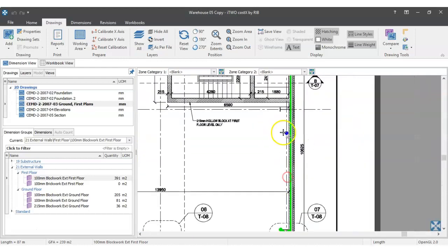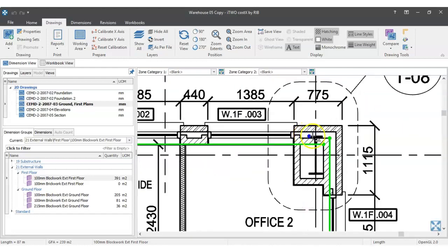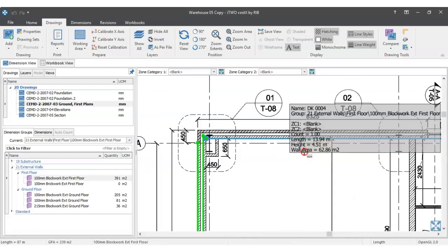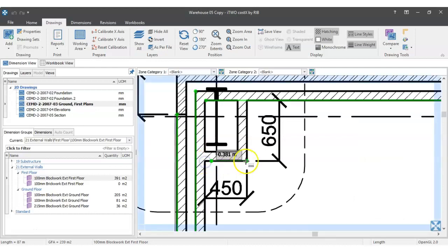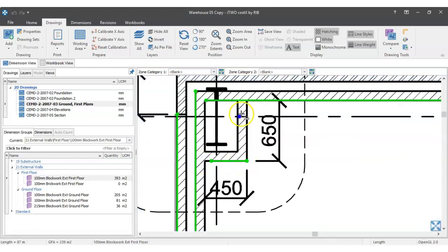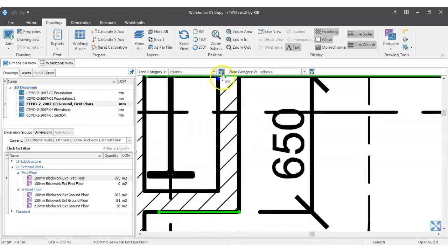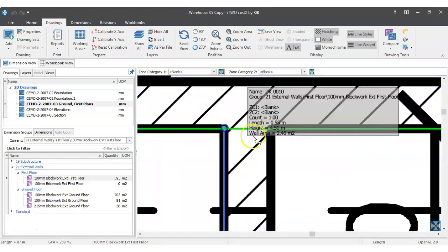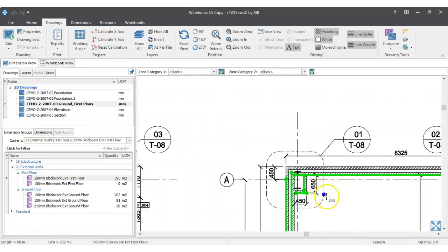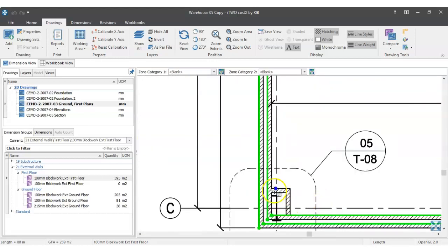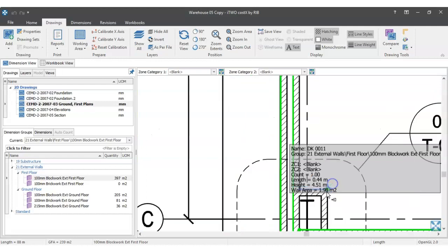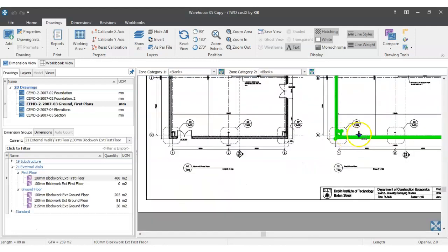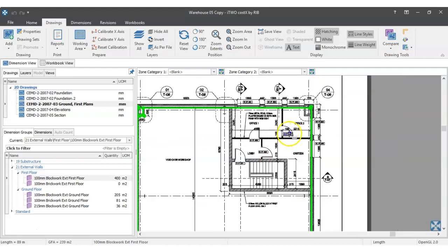And do I have everything there measured from external block work, 100mm? I think I do. A couple of more corners here to measure. You know, when I go up there and try to measure from that point, it wants to click on that line. So you're best off clicking from the point that's not overlapping. And then our last corner items here. Okay, so there you go. I'm happy enough with that.